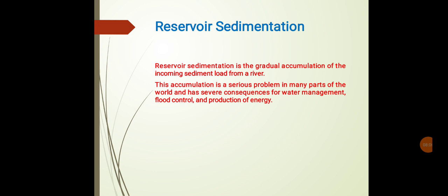So reservoir sedimentation is a huge problem, which is why every year we are desilting our water source structures. Every year during the rainfall season we receive water that brings mostly silt and clay particles, as well as bed load particles like gravel and sand, which are deposited in our storage structure.